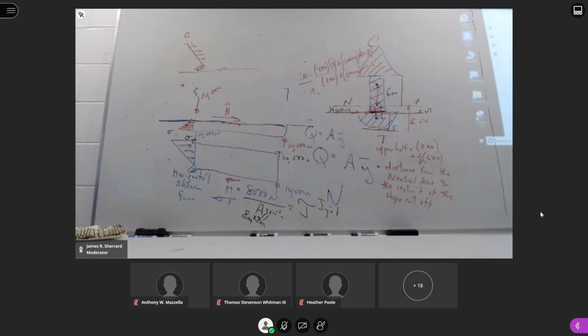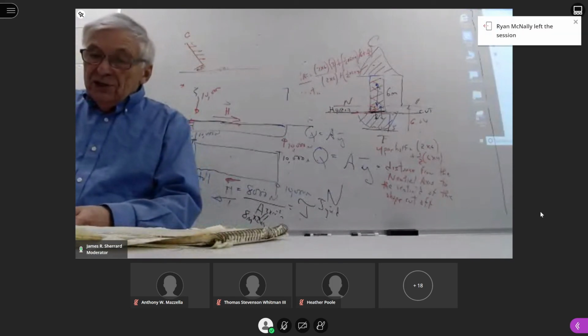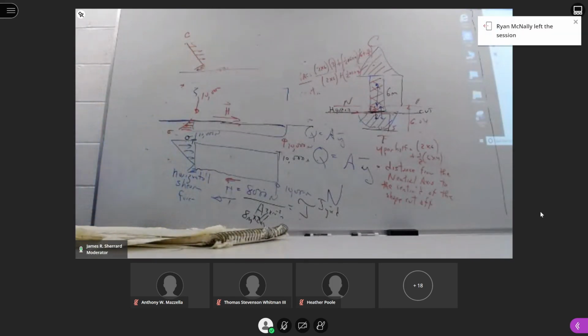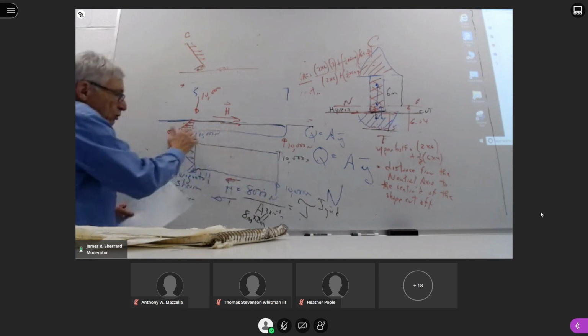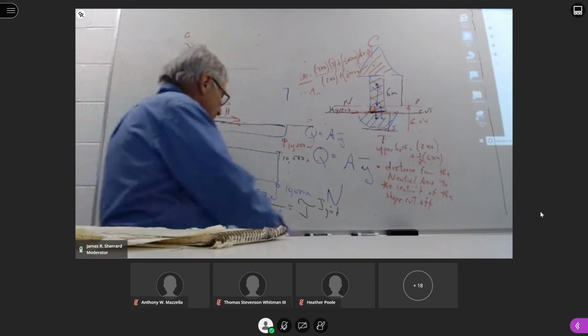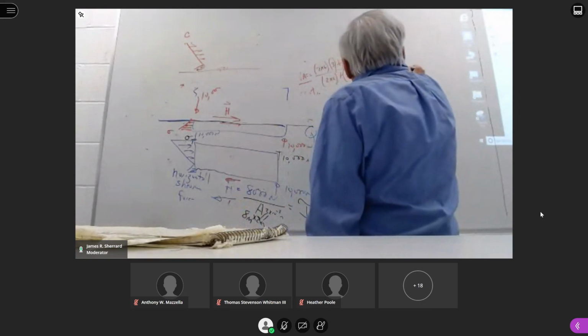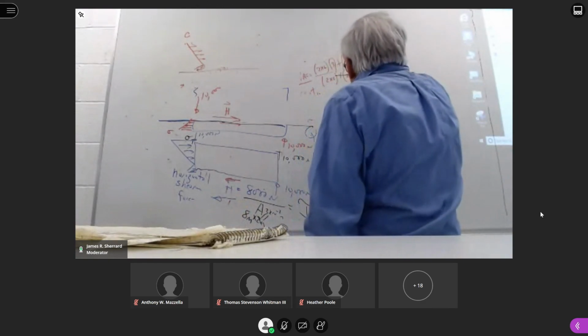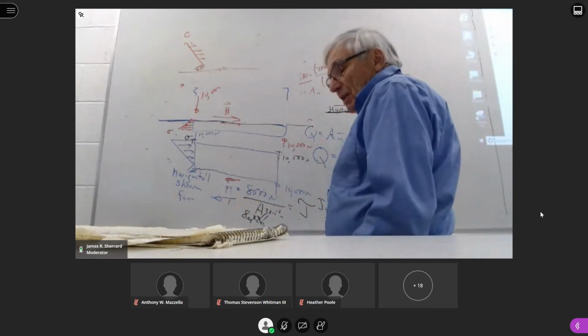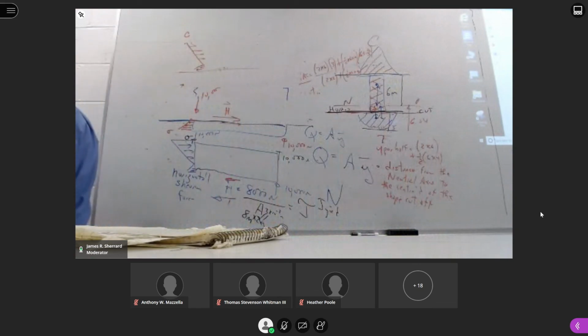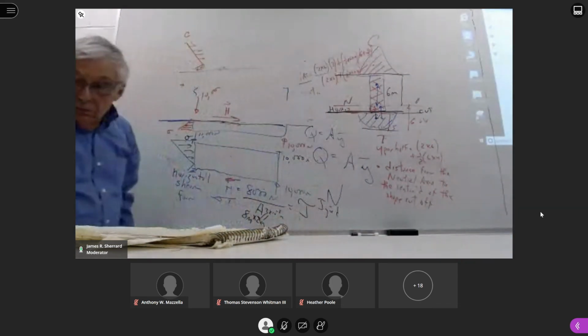we're going back to the same cantilever beam that you just had on the last quiz. So the cross-sectional area is the same. The neutral axis is the same. The tension and compression areas. The vertical shear forces. This time, instead of cutting this here, I want you to cut it here where the triangle joins that. And I want you to sketch for me a free body diagram of the upper half.